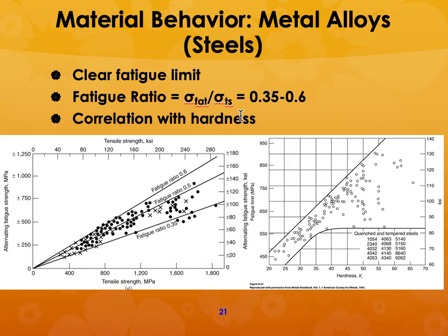So that means if you typically apply a maximum of 10% of the tensile strength, 10 to 20% of the tensile strength, you are in a safe stress level. But if you start going up to 30, 35, 40%, then you are playing with fire.